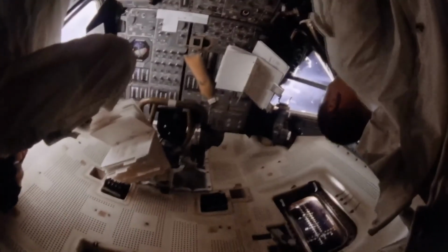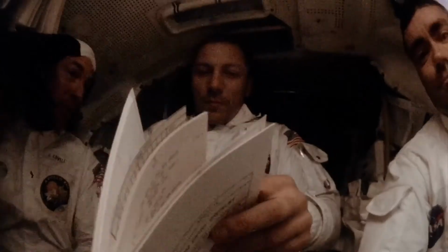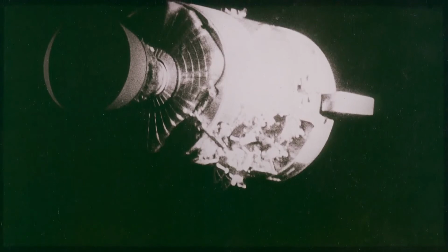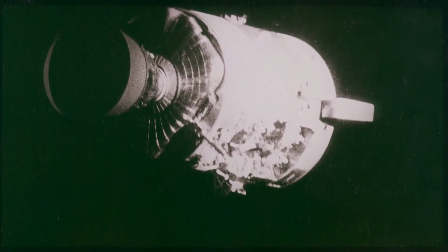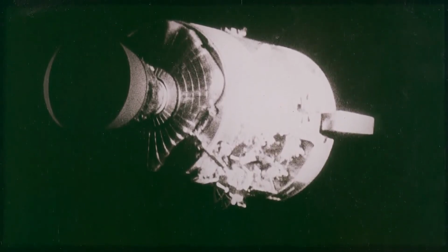As for redundancy in the case of an AGC failure, and unlike Apollo 13 without the LM or its onboard PGNS or AGS on its route back to Earth, NASA says that the command module had a second control system that could operate independent of the other systems, called the Stabilization and Control System, SCS. This Stabilization and Control System could maintain altitude and allow the crew to make accurate maneuvers and, if necessary, even manually control the SPS engine. In other words, NASA says that if necessary, the astronauts could have hand-flown the CSM 240,000 miles back to Earth with nothing more than hand and eye coordination.